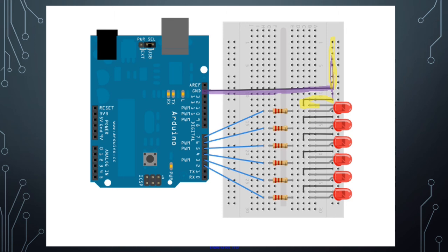Okay, so we've connected the LED now to the ground on the cathode side. Remember, that's the negative side or the straight side of the LED. And on the anode side of the LED, we're just going to put it in the row right below the one it's currently in. And this is easiest because with LEDs, the anode and cathode are typically close together. So it just makes it easier to plug them into rows that are right above each other, because we can do that, right? The connections are separated by row. And so that's perfectly fine to do, again, as long as each connection's on its own row.